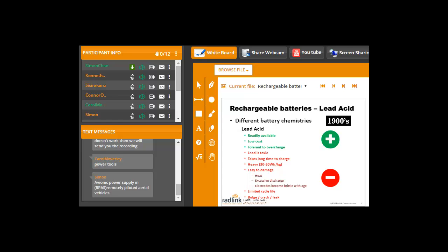In terms of charging, you have to charge it with constant current followed by constant voltage. What it means is that if you've got a cell that's rated to a particular capacity, you need to charge that cell using constant current until the cell's potential difference between the positive and negative terminals reaches a particular value, at which point you switch to constant voltage charging to finish the charge cycle. I'll explain a little bit more about this in a few slides.